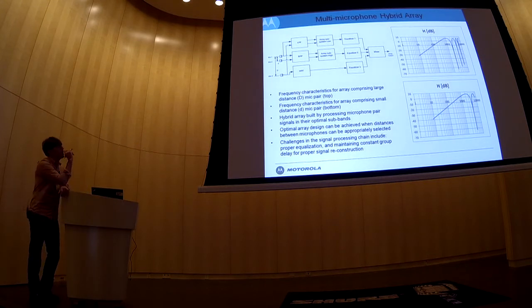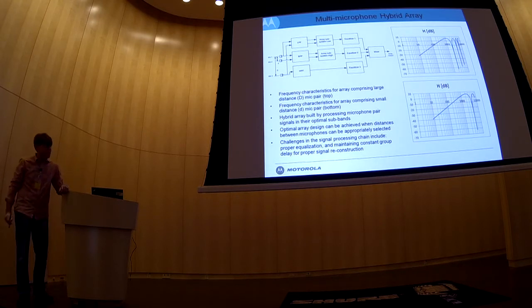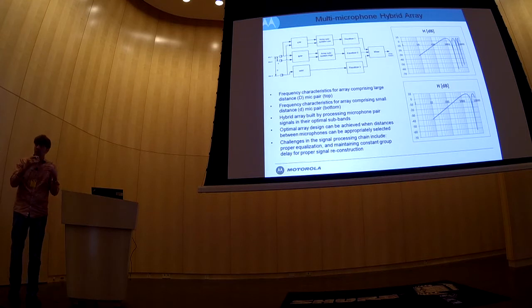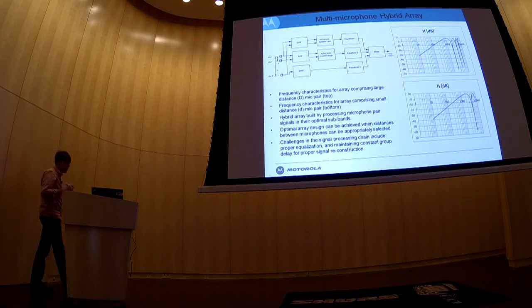I wanted to mention this. This isn't so simple, in the sense that the system engineer that works on this will have to make sure that the equalization is done properly, that the group delay on all the branches is done properly, so that when the final mixing occurs, the signal recovers and reconstructs properly.